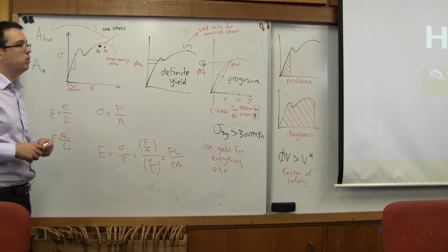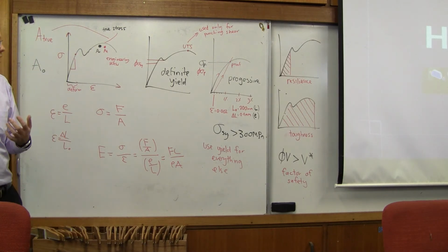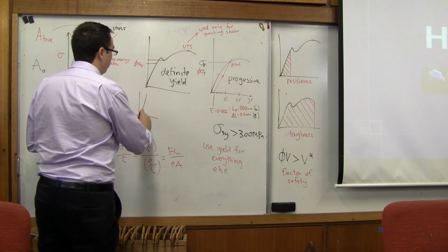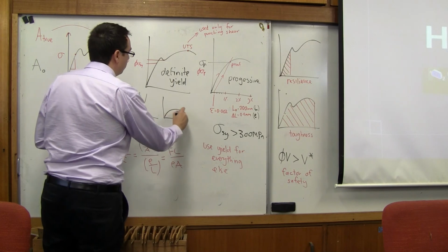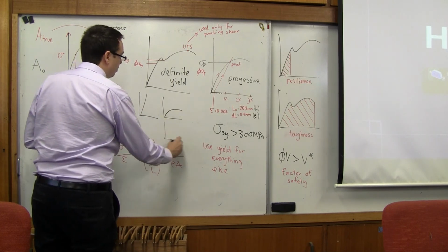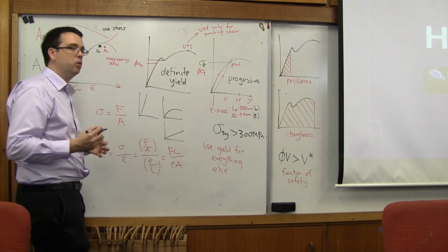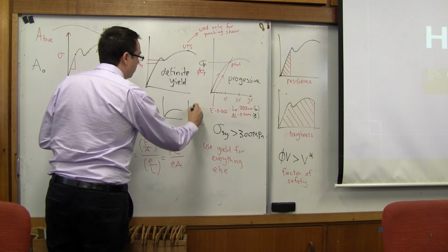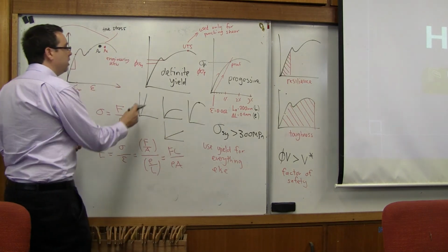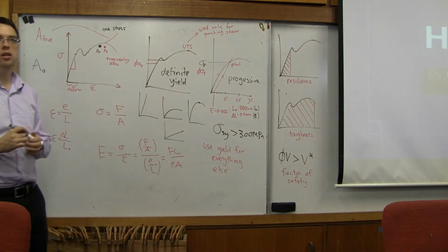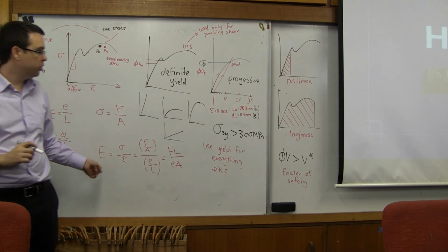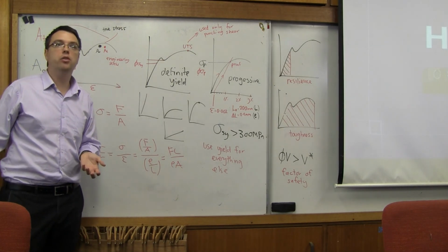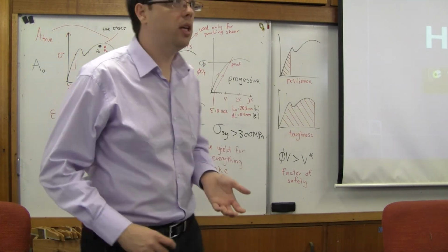I did say that was the last thing. It's worth noting, and we'll have other examples in the book, that we can tell other properties. We can tell things like how a brittle material looks like this, a ductile material looks like that, and something that's very elastic looks like that. The strength is measured by how high the material is. So there's different things that we can measure. The stiffness is the level of Young's modulus, how steep the gradient is. I think that's a pretty good summary of everything we need to know about stress and strain.